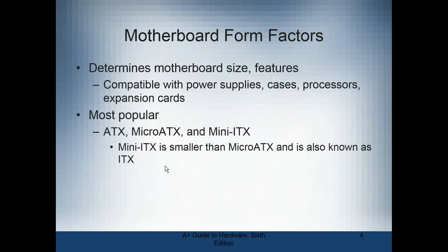The most popular, the ATX, the micro ATX, and the mini ATX. The ATX, there is a BTX, and we talked about it, I think, last time. The BTX, everything is parallel. It actually is better for heat dissipation, for airflow across it. The ATX, the typical physical first look, the memory slots and the expansion slots will be perpendicular to each other, which could affect airflow, may not.